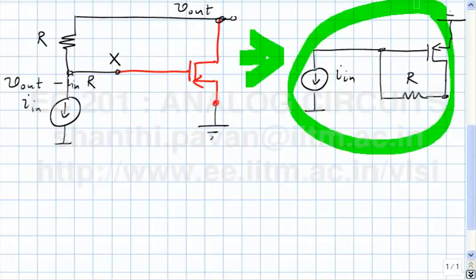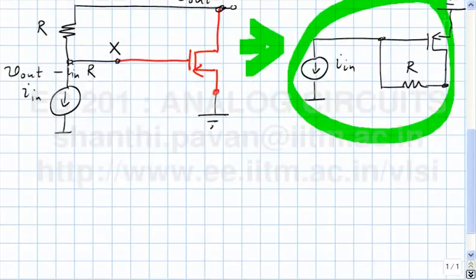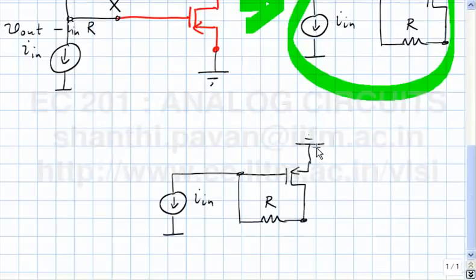Can you now help me figure out what the real circuit should look like? First you must bias the transistor. The source of the transistor must be at incremental ground. Alright. Can I connect the source to real ground? Why? So we expect the quiescent current in the transistor to flow like this. And if you connect the source to real ground, obviously current can't flow away from ground if all the other sources are positive. So this must be connected to the highest potential you have.